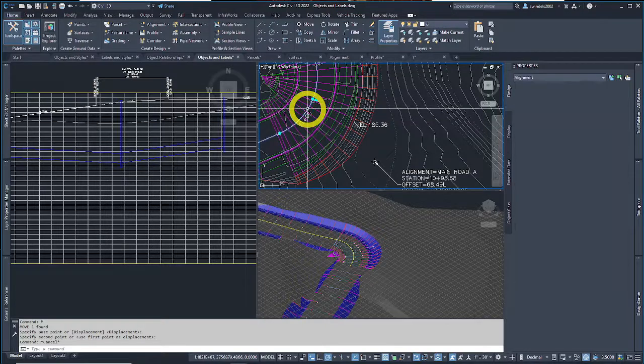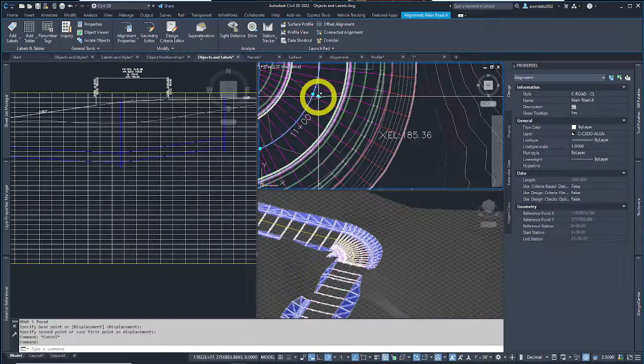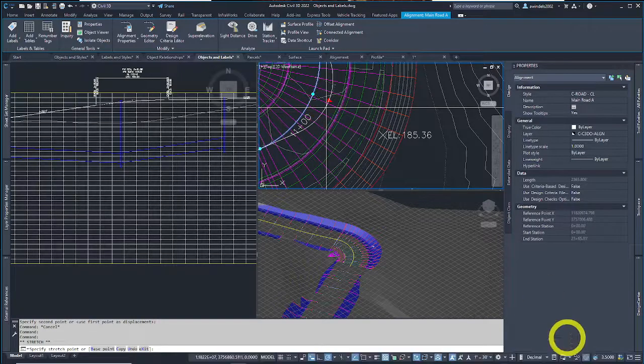I'm going to pick the center line of the alignment, and I'm going to click the triangular grip to drag it to the point near the west edge of the road. So look at figure 2.7 on page 30, and let me just pull this triangular grip a little ways out. Let the corridor model give it a second. It'll change everything here and here.